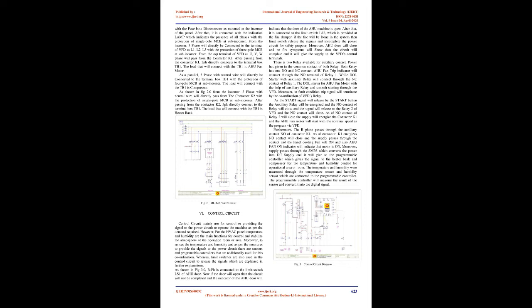5. Power circuit. Power circuits are mainly used for providing power with protection. In the power circuit, there is a three-phase 4-wire system with earth ground. AHU fan motor, condensing unit, and heater bank are calculated as the load of the HVAC panel. VFD is used for better speed regulation and smooth starting of the AHU fan motor. The main supply is driven from the main distribution panel with 415 V.